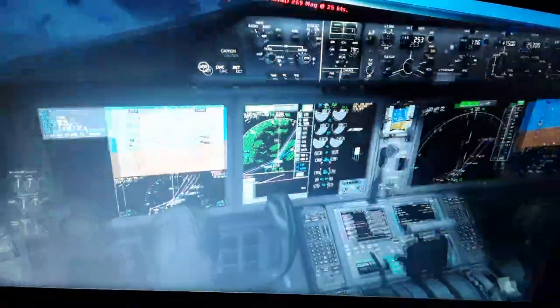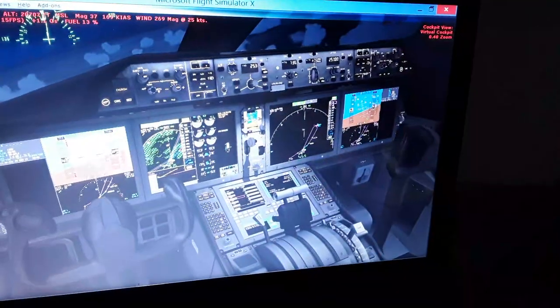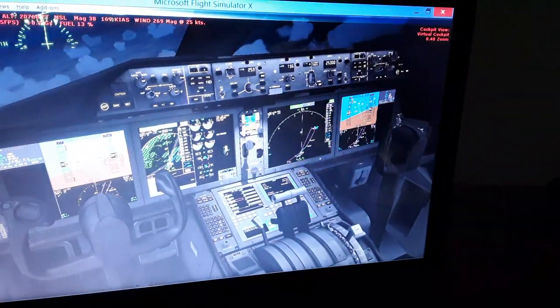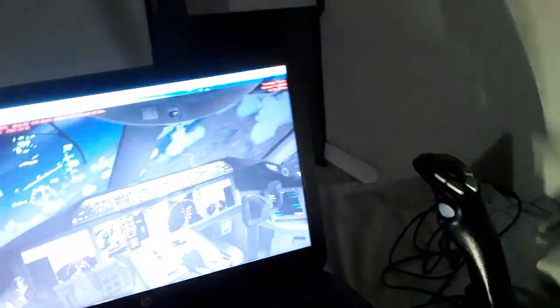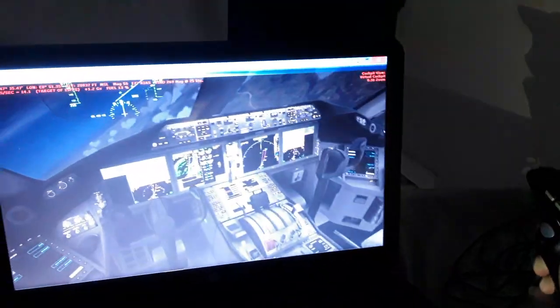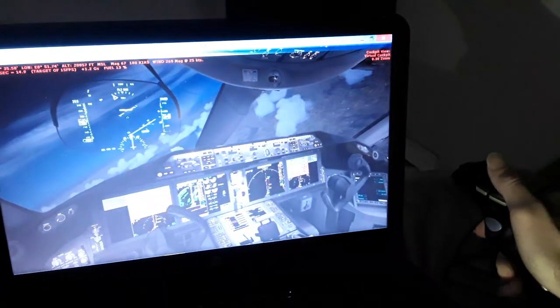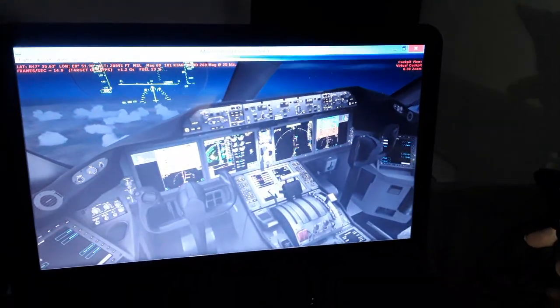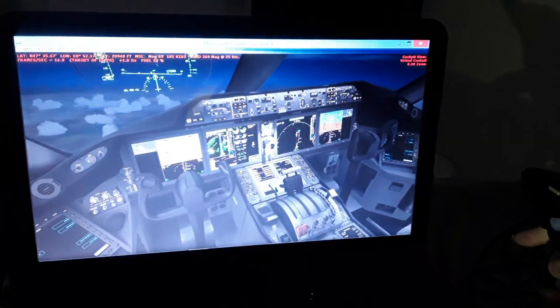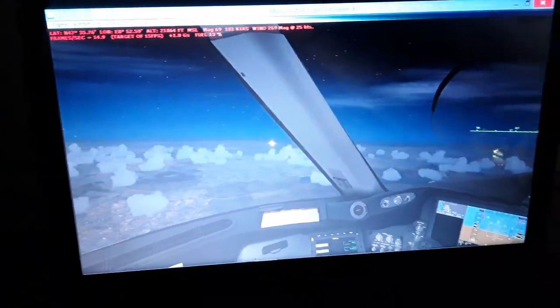Here we're gonna level off for a couple of minutes, follow the flight plan. We can also decrease the rate of climb, so we're gonna make a turn right now. As you can see, manual turn. We keep flying manually. Also use a little bit right rudder, which helps to align a little bit faster. Now left rudder, leveling off. So now we're flying more level.